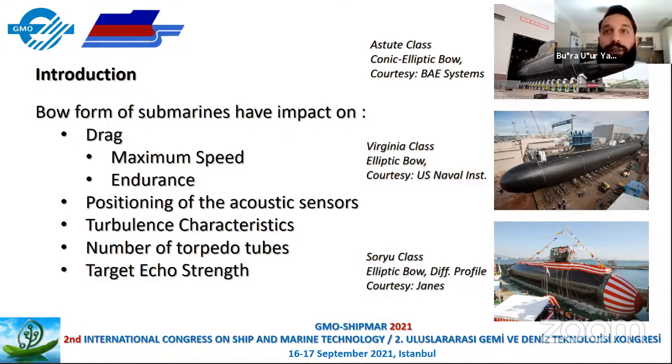In this way, it is aimed to prevent turbulent flow in the forepart where the cylindrical sonar array is positioned, thus enabling the sonar to operate effectively. Even if a blunt nose shape enabled designers to have more torpedo tubes, it was found that the blunt forebody shape results in an extensive local adverse pressure gradient, and this becomes the basis for the drag coefficient no longer decreasing with an increase in flow velocity and remaining constant after a critical velocity.